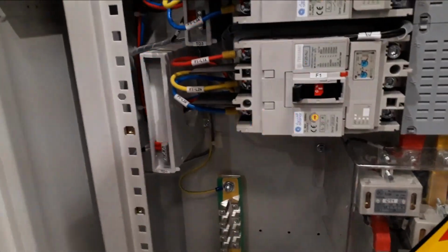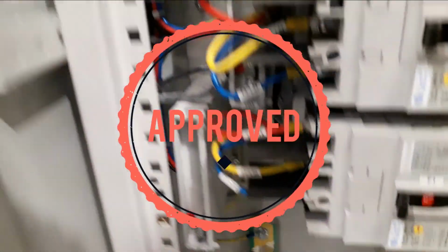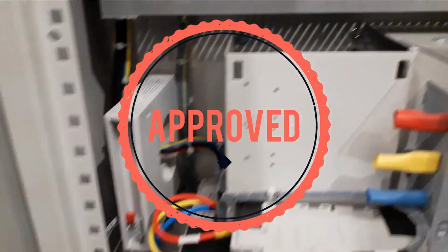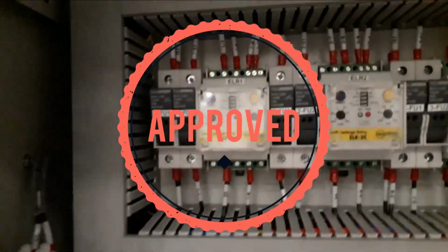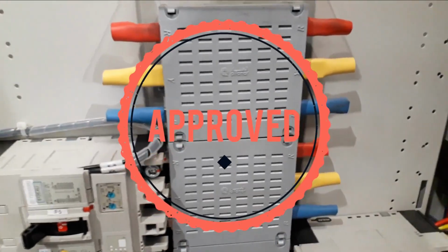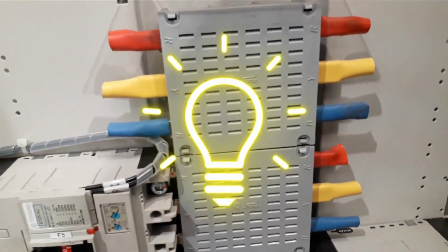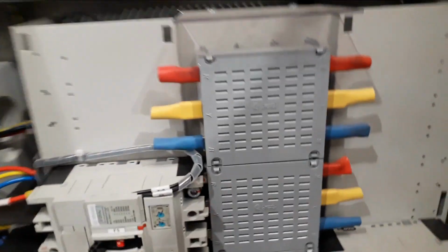As you notice, we have the toroid here. This is the toroid. What we have here is connected through our ELR. Okay, so that is the sensor to identify the fault. You will find the connection from here. So you will find RYB also here, meaning R is line 1, Y is line 2, B is line 3. Okay, so that is RYB, red, yellow, blue.